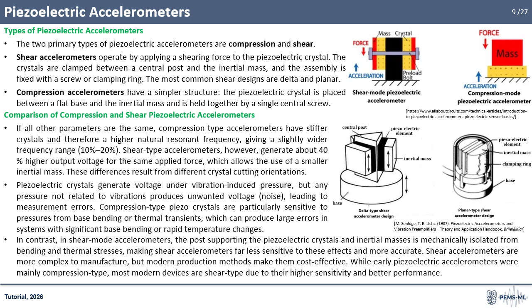Although shear accelerometers are more complex to manufacture, modern production methods make them cost-effective. While early piezoelectric accelerometers were mainly compression type, most modern devices are shear type due to their higher sensitivity and better performance in demanding industrial conditions.